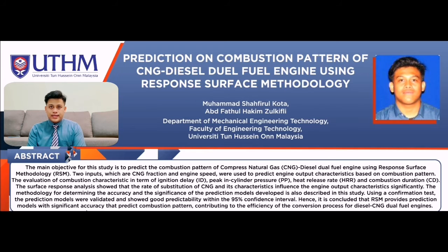The response surface analysis showed that the rate of substitution of CNG and its characteristics influenced the engine output characteristics significantly. The prediction model for ID was suggested to be a linear model, while PP, HRR, and CD were suggested to be FI models. Using a confirmation test, the prediction models were validated and showed good predictability within the 95% confidence interval. Hence, it is concluded that RSM provides prediction models with significant accuracy that predict combustion pattern, contributing to the efficiency of the conversion process for diesel CNG dual fuel engines.